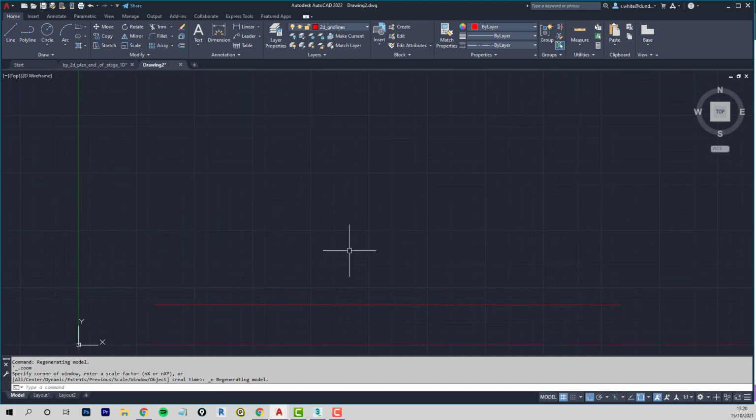So we use a command called line type scale. It shortens to LTS. Enter. So let's see what 10 comes out at. At the moment it's set at 1. Let's say 10. Still too many breaks in the line. Okay. Want to use that again, you just press enter again, put in another number. So it's a bit trial and error with line type scale, but that's okay. I think that's probably about as many dashes as I would draw myself.